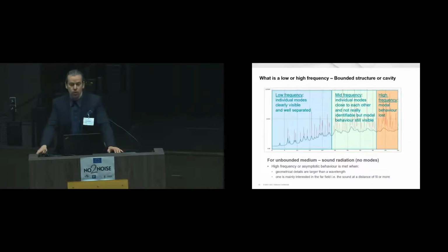So when I say low and high frequency, what do I mean? The behavior of the systems is quite different in low and high frequency. In low frequency, usually when you have a structure, you have individual modes that are clearly responding independently. They are well separated. They can be observed when you're doing a frequency sweep.